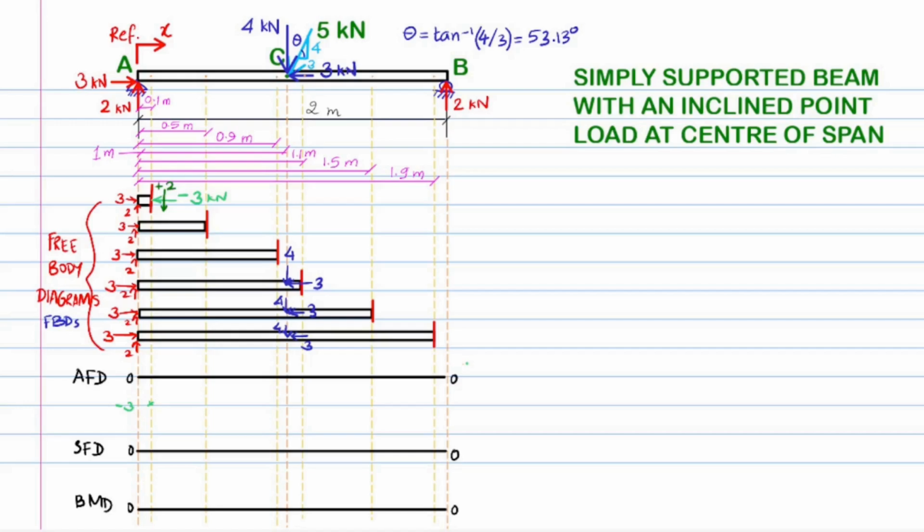We see that the combined effect of the shear force and the reaction force is to create a clockwise couple. Hence, we consider it as positive in sign. Lastly, the reaction force at A creates a sagging effect of bending about the section, and hence we consider the resistive bending moment as positive with the value 2 kN times the distance x. Let's say the distance is 10 centimeters or 0.1 meter. So we have the bending moment as plus 2 kN times 0.1 meter, and that's equal to plus 0.2 kN meter.